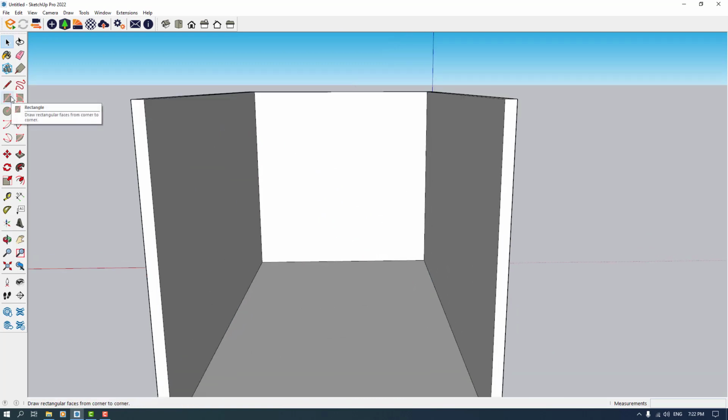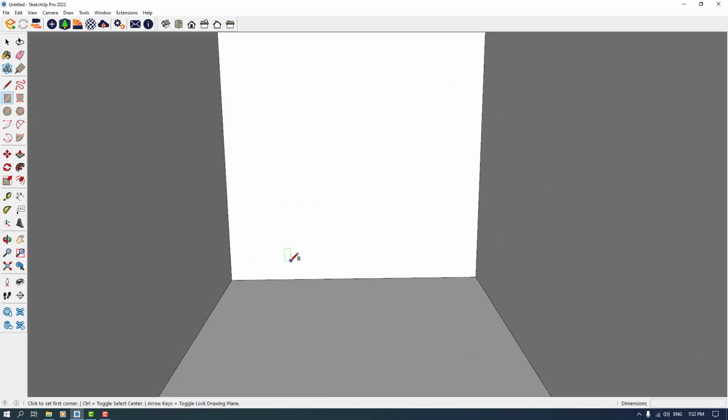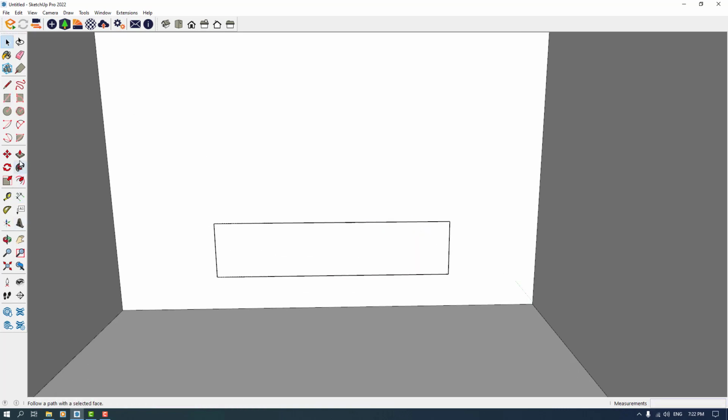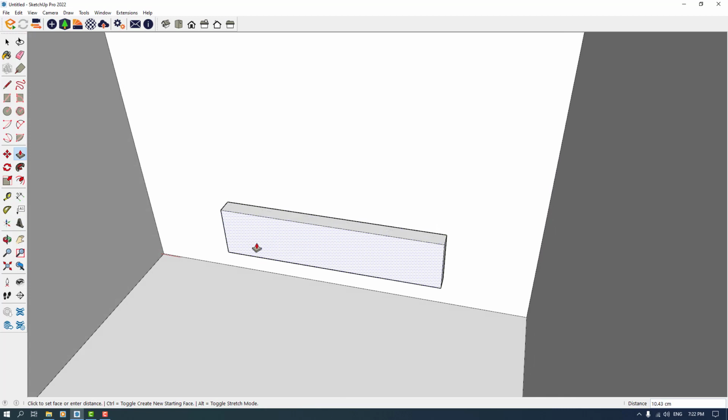I start with some wood panel boxes. I'm gonna click on the rectangle. I draw some rectangle with dimensions about 156 to 36, like this. I'm gonna extrude it a little bit, like that. And it's something about the depth of the TV wall, maybe 30 is good.